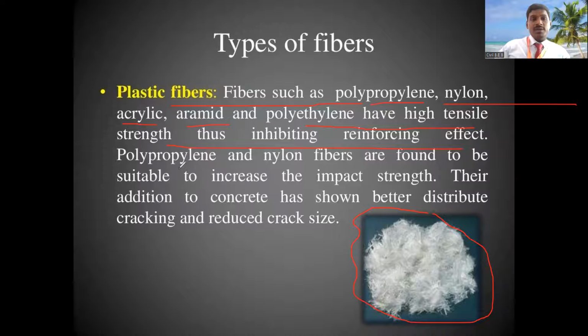Then polypropylene and nylon fibers are found suitable to increase the impact strength. If we use these fibers, the impact strength will increase, and their addition to concrete has shown better distributed cracking and reduced crack size.